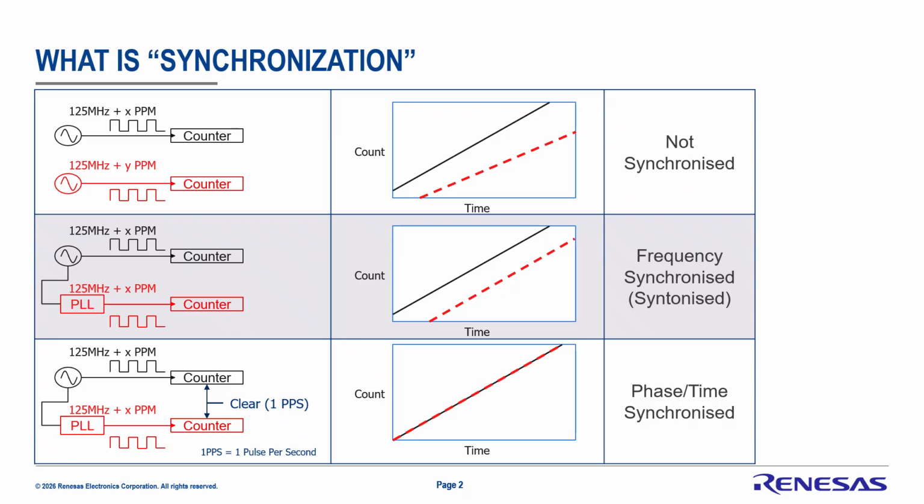In this case, a clock is now feeding the same clock with the same error into a counter, and another counter would have the same clock and error represented at its output, so that if you sampled those two counters at any point in time, although they may not have the exact same value, they definitely would have the same static offset relationship between them. In other words, they would be incrementing at relatively the same pace.